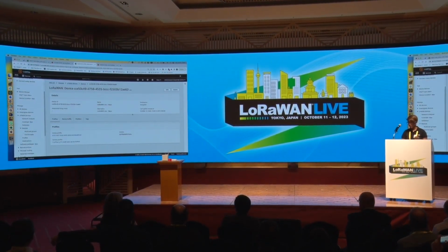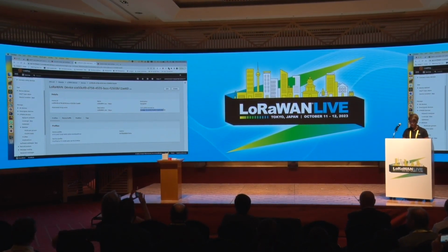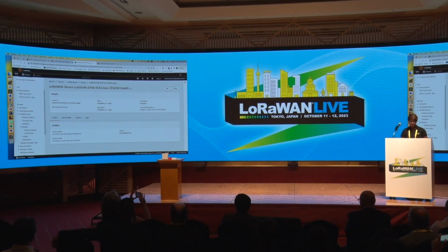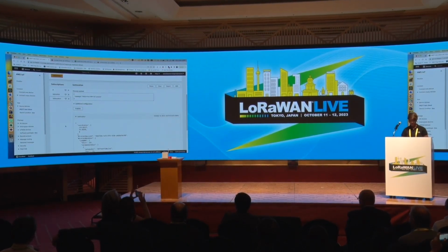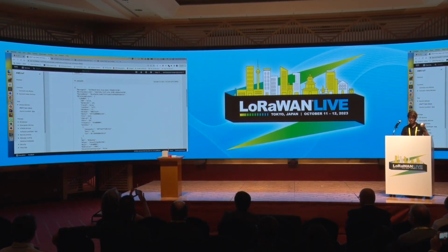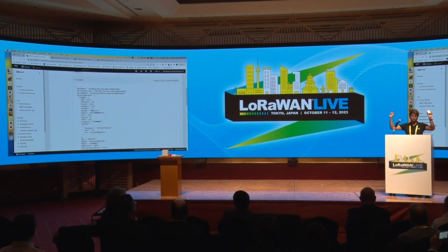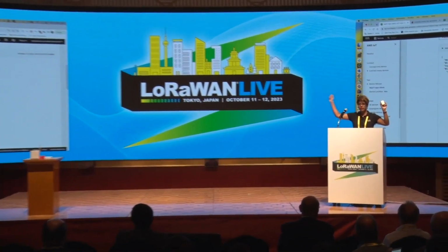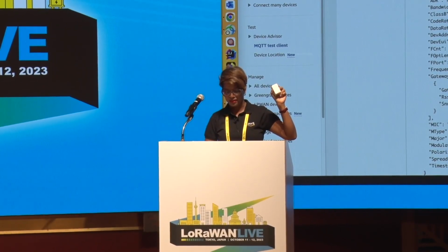And how I'm saying that this is the live data, because look at the last uplink. It's the current timestamp. I will show you how the data looks like, because that's a bit more interesting. So this is the payload that's coming from this Torque device, and the gateway is basically forwarding the package to the LoRaWAN network server in AWS. The interesting thing here that I want to highlight is the payload data. Look at the size of the payload data. It's just a small packet.